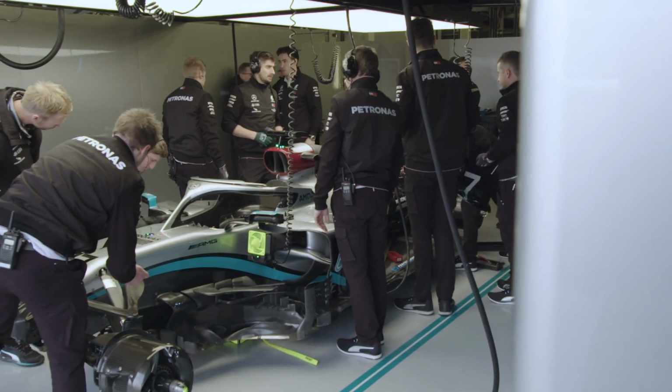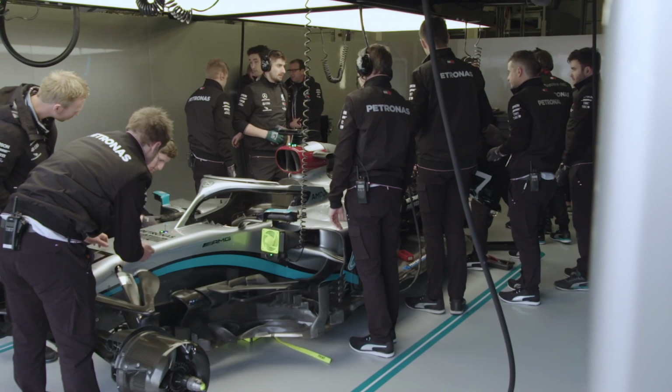And when we talk about the pressures involved in those sort of things, very locally, you can erode the pistons, and actually the amount of force that then puts through the whole system can be quite horrific. How can you actually tell, though, it's knocking? Can the drivers hear it, or is there any sensors on the car that you can see? From the engineering perspective and looking at the data perspective, yeah, we can measure it. We can measure it through cylinder pressure, and you can actually measure it through the acceleration of the cylinders. You can feel that knock, that pressure wave going through the cylinders.